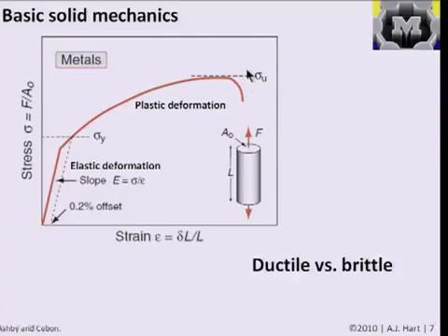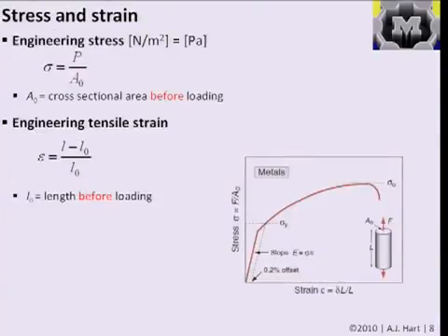So you remember the difference between ductile materials and brittle materials. Ductile materials absorb a lot of energy or have a large plastic deformation range, so something really stretchy is a very ductile material. A brittle material has very little plastic deformation, something like a piece of chalk that would snap because of the nature of its characteristics. And this can be a pure material, a single crystal, an alloy, or, as we'll see today, just an individual nanostructure. We certainly see some interesting effects based on that.